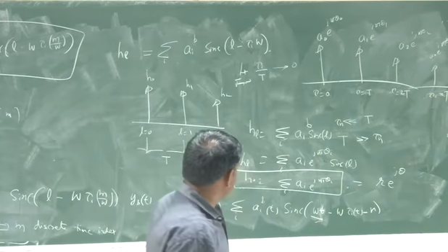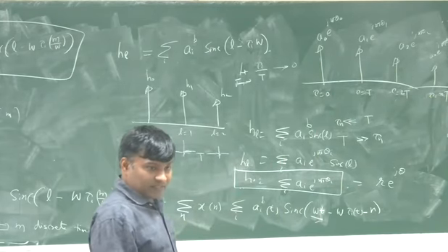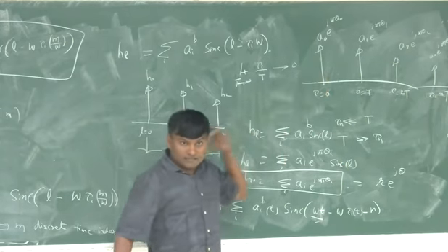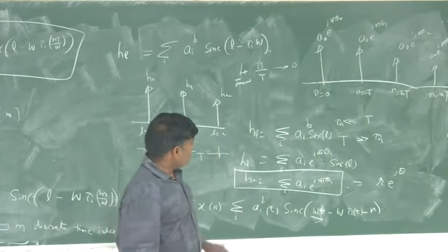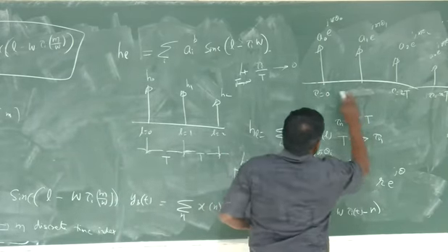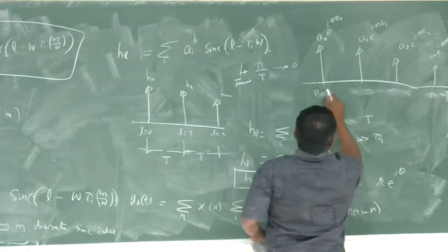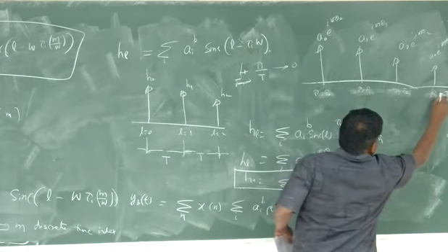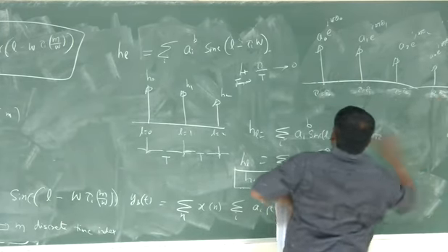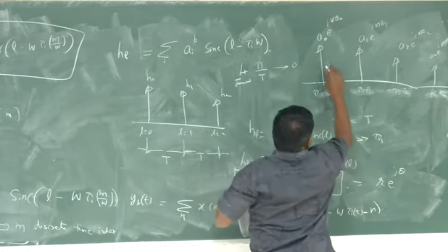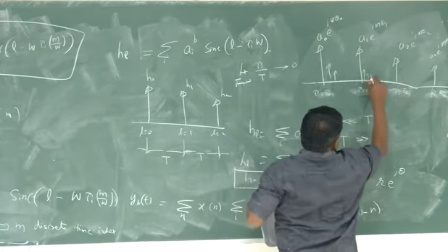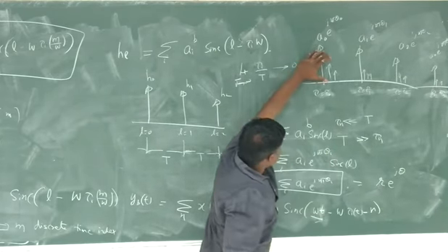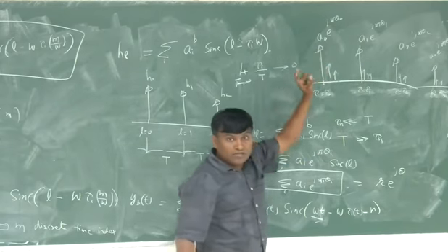Of course, this is intersymbol interference. The response would be the convolution of this profile with the transmitter pulse. But in real life, you will never have a channel following any of these nice profiles. Usually, channel taps occur like this. They occur in clusters. All these clustered rays will contribute as one effective h.